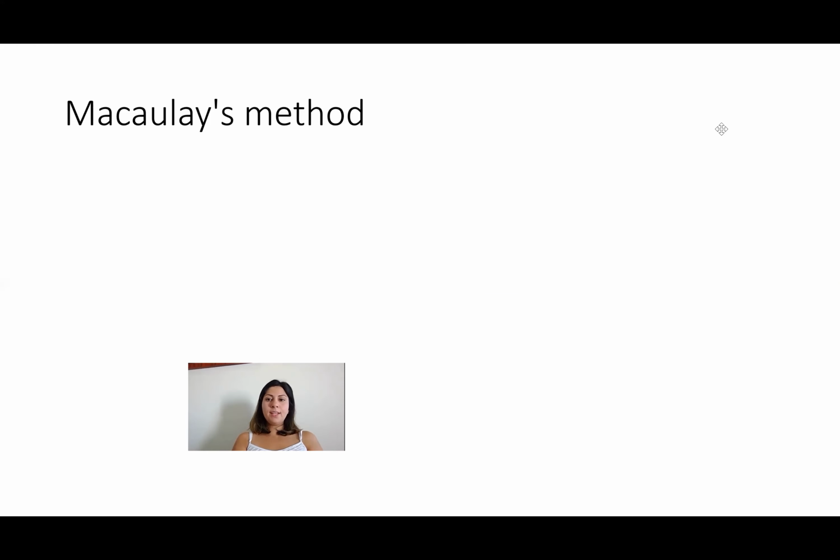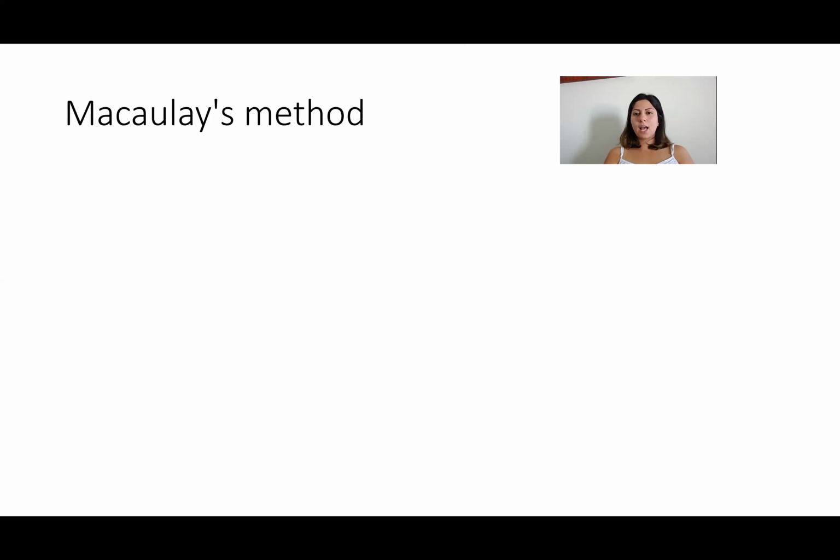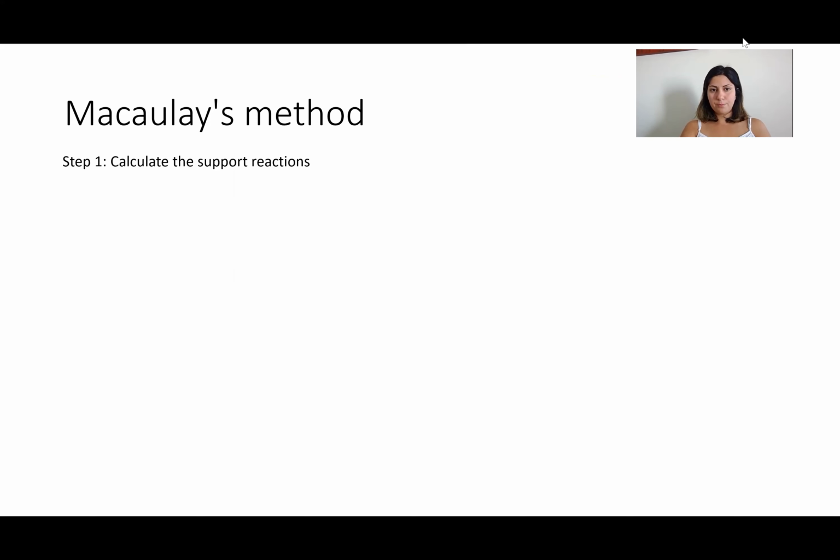Okay, now let's learn how to use whatever we learned so far to use the Macaulay method. Step 1, you need to calculate the support reactions. As you know, this step is always the first step that you take in all the analysis that you do.